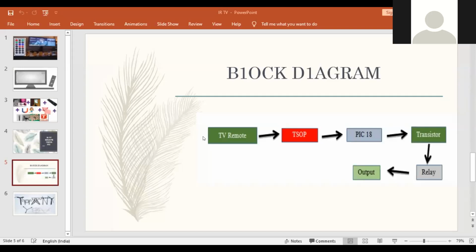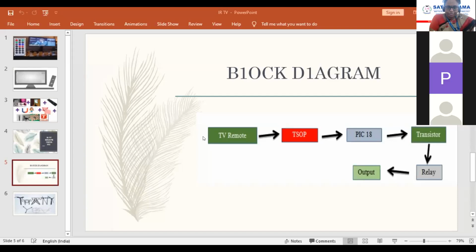If we press the volume up button, the binary value reaches the LED, which sends the binary value to the microcontroller in the television in the form of infrared waves. The manufacturer programmed the microcontroller to accept the binary value and decode it to get the desired output, so the microcontroller decodes it, and finally the television will change the channel which we like. That's it, ma'am.